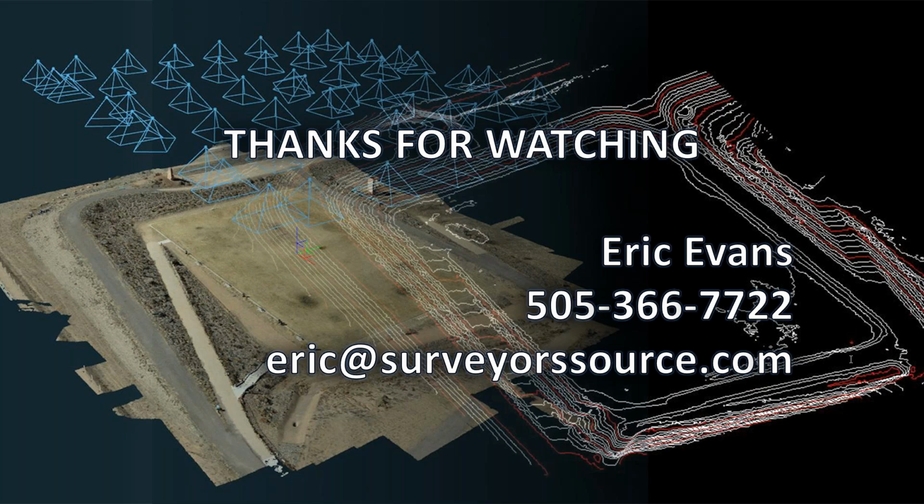So this works for most cases. Or if our area is very big, then we might use 6 feet or 2 meters for the grid cell size. So that brings the triangle count down a lot, so it helps a lot for other programs to manage.